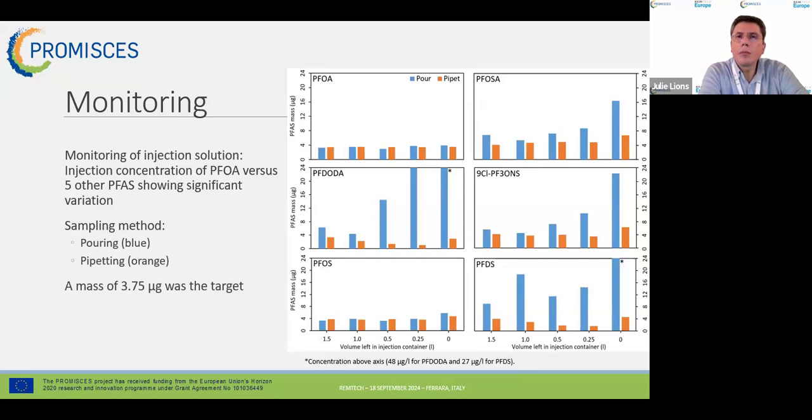Of course, it is known that PFAS do this, but we thought that because we were stirring the injection solution and thereby breaking the air-water interface, this wouldn't happen or wouldn't happen this extreme. Unfortunately, we found that it's otherwise. It's even sometimes so large that the concentration at the bottom of the water column gets lessened as well. You can imagine that this has a large effect on the transport characteristics of the solution, and it also makes it more difficult to close the mass balance.